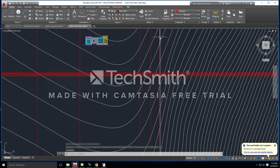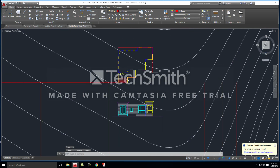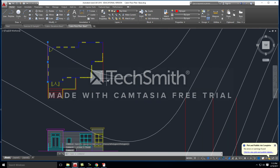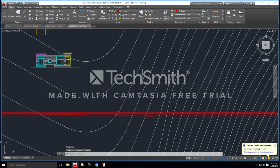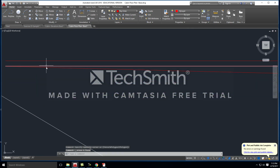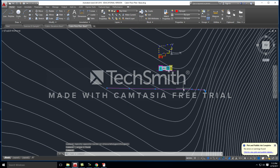And now I can go ahead and delete all of the lines that I just created. All right, I don't need any of these lines here anymore. Don't need these either. I actually originally set these up so that I could line up my elevations, okay? But from here I can get rid of all of these lines, including all of my ray lines that we see here. Okay, and now notice this line is now representational of our actual slope in topography.